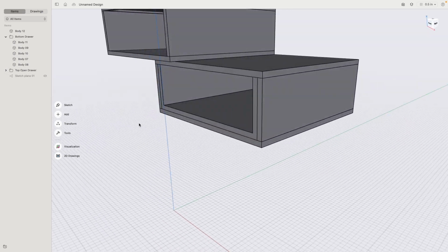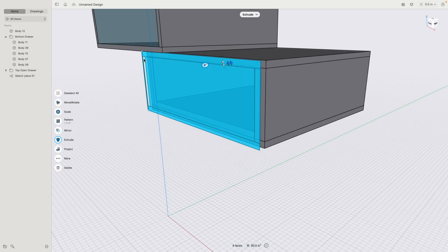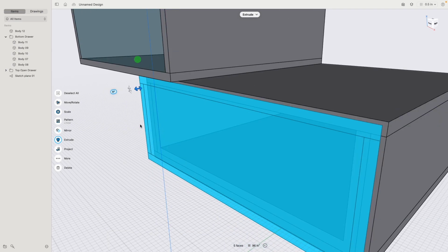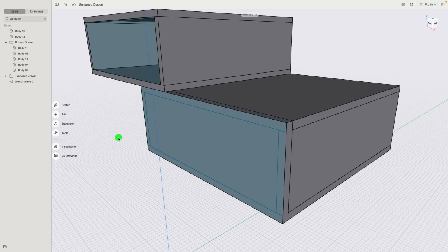You see? If you have 2 or 3 faces, you can very easily select them via the mouse by clicking on them. If you have more faces, as you see, it's easier to just do a draw select. Now we can turn on this first sketch here and then select all these individual faces. There we are. And extrude this back by 1/2 inch. Very nice.